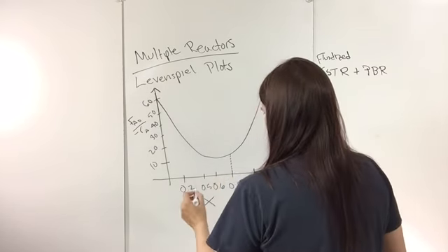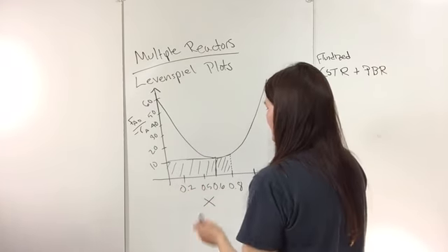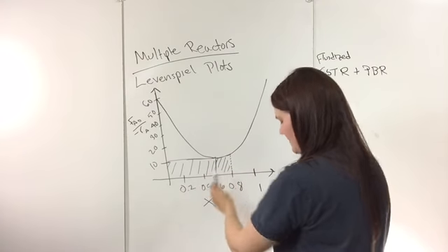So to get the smallest amount for 80%, this is actually what you would want, because for your CSTR you want to come up with the smallest possible area on this. So this would be the CSTR. And if you change the order of these, so say you put the PBR here, then it would be this entire area for that, and then the CSTR would just be here.